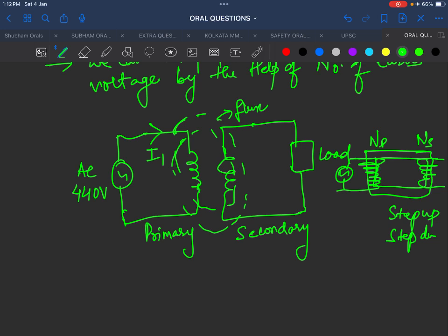Due to the rotating nature, you know by electromagnetic induction, when a current carrying coil varies in a magnetic field, it produces an EMF, the rate of change of flux. So due to this flux linkage in the secondary side, there is an induced EMF, denoted by E2, and V1 is your supply voltage. Due to this induced voltage, current starts flowing if you connect the load here. If you connect the load onto the secondary side, another current will flow, that is I2.